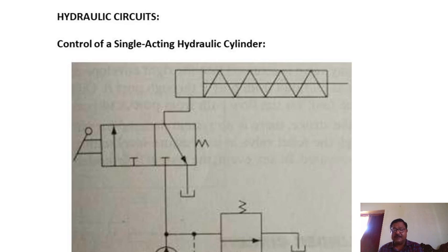And generally, problems encountered by the designer may be movement of machine tool table and machine slides, press ram, and mechanical transfer of loads. These different problems can be solved by using hydraulics, with proper design of the hydraulic circuit. For instance, in a machine tool, the different events or activities involved are loading and unloading of jobs, clamping and declamping of jobs, and forming operations such as machining, pressing, movement of materials, tools, etc.